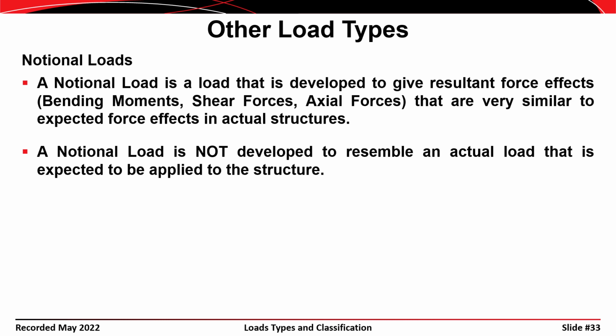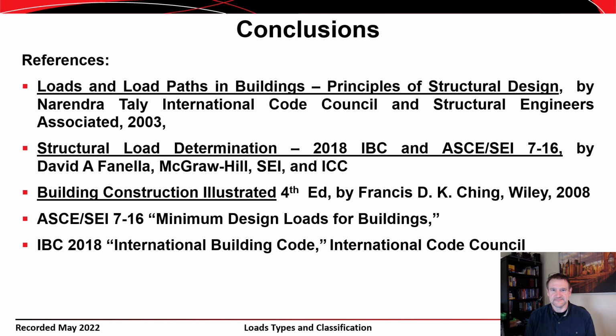You would have to develop a computer model where the building is a little bit out of plumb. So rather than considering that explicitly, a lot of engineers will put a notional load into their model, usually a lateral load, that gives bending moments, shear forces, or axial forces that one might expect due to the initial imperfections or initial out of plumbness of the building. Usually, these notional loads are prescribed as a percentage of the gravity loads. So if you have a dead load and a live load given, you might say that the notional load is a percentage, 1% of those gravity loads, for example.